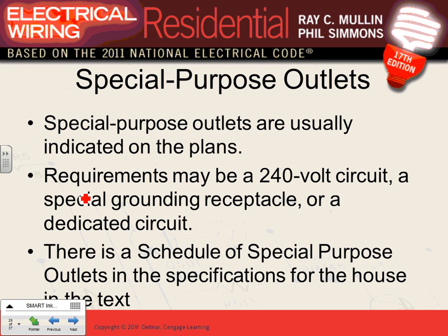Just a couple of things about the devices. Special outlets. There's special outlets, guys. The most common convenient outlet that we use in the US is 15 and 20 amp. Everything is 15 and 20 amp, typically, 120 volt. These are 90% of your typical outlets.